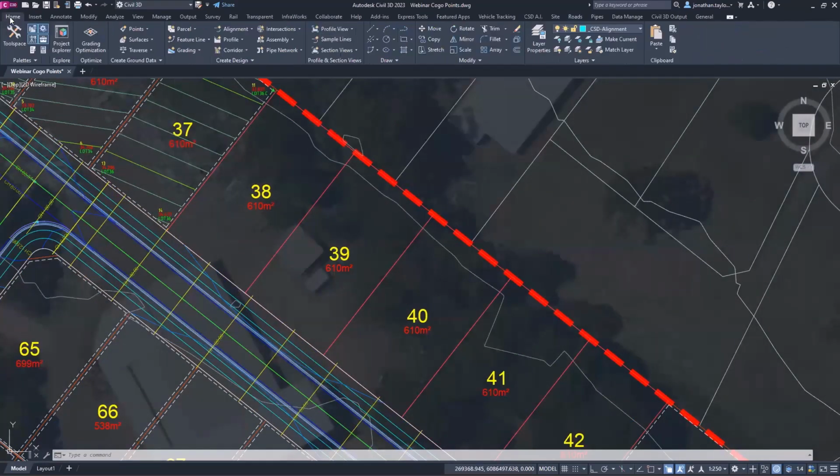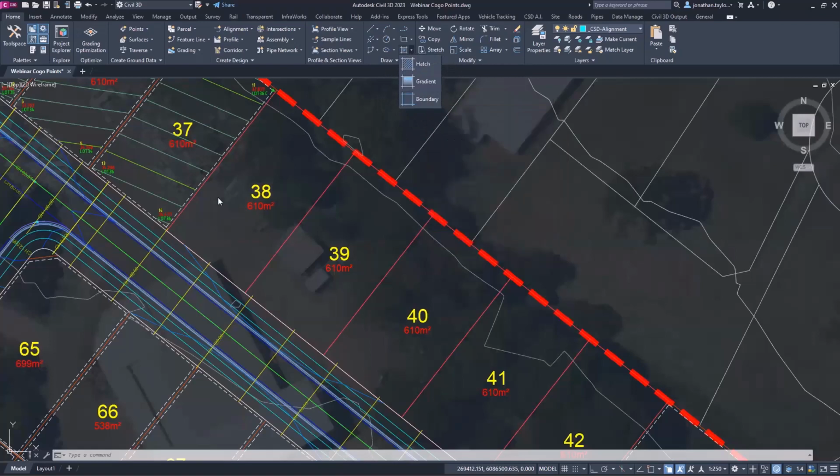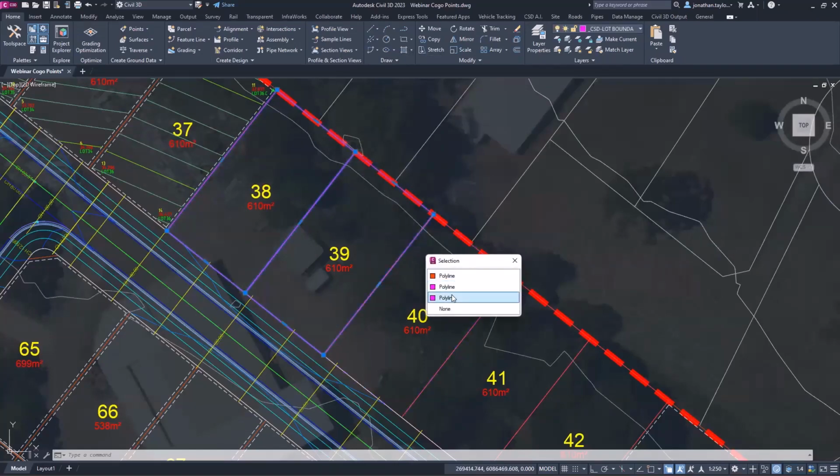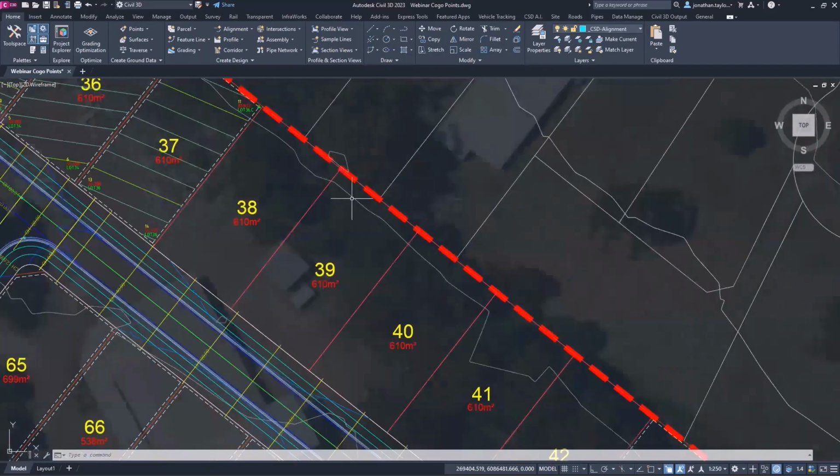I will just highlight, when you go to the Home tab on AutoCAD and BricsCAD and Civil 3D, they're all going to be the same. You will find that there is a boundary tool. This is like creating hatching, but it's called bpoly, or you can type BP in your CAD environment. It'll bring up the same thing. That will draw a boundary polyline as if it was going to be flooding it with hatching. So you can use that tool to generate polylines, assuming you've turned off some of the content inside. And if we just use the selection cycling tool, you can see I've got these polylines already generated for my lots. Now, the problem is the offsets.